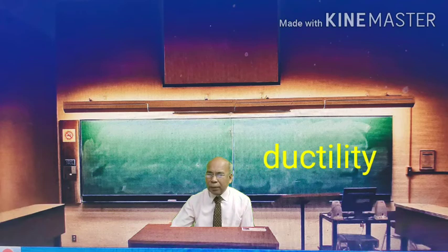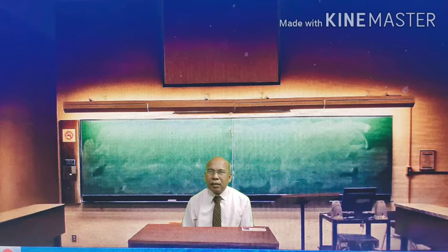Ductility, the property by which the material can be elongated as a thin wire or thin rod, will be improved due to hot working, since it's heated to a high temperature. Malleability may be increased, but there's no strain hardening. Less force is enough to deform the metals since the temperature is more, and the equipment required for forming the metal into different shapes may have less power.